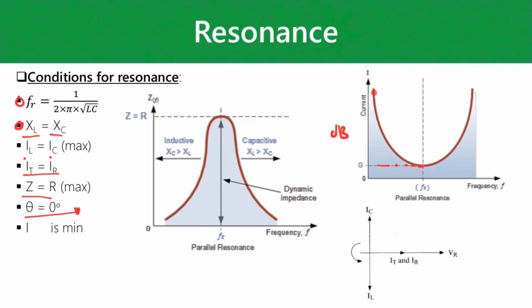In this sense, it is going to be a little bit more difficult to get that half power frequency on this curve, but you can probably estimate it around about there. Say minus 3 dB. Okay, minus 3 dB. And you guys will notice that that is essentially a band reject filter. So that's essentially what we're sitting with here.